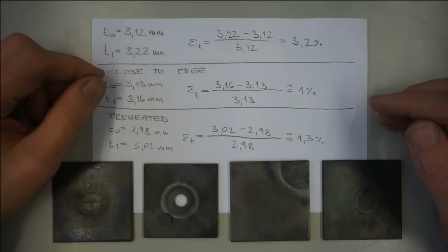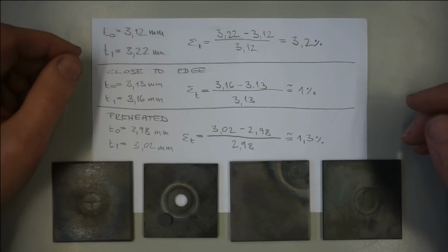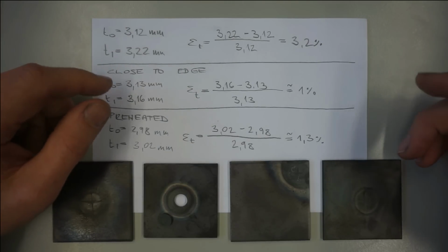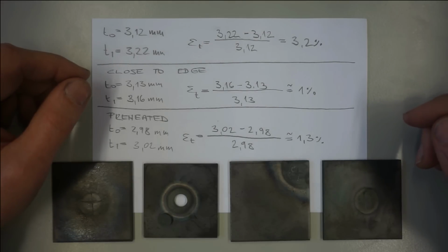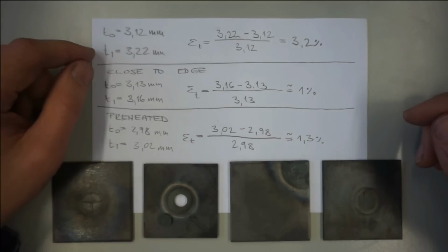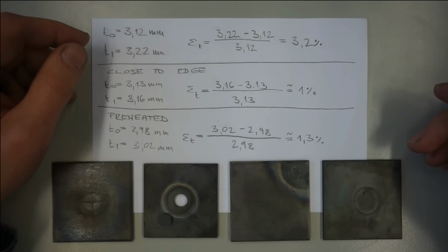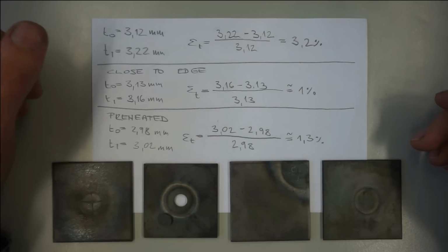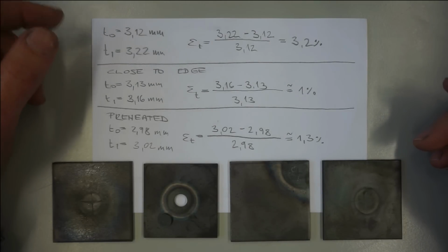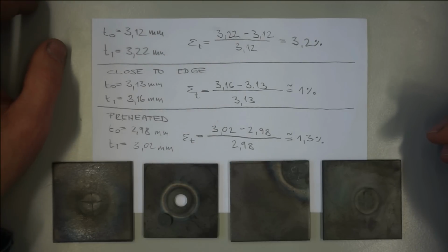You can try these experiments for yourself if you like, with steel or other metals. Also, you can vary the sheet thickness. Too thick sheets though are problematic to heat through, while too thin sheets tend to buckle. Nonetheless, if you compute the thickening in percent like we did earlier, you should find similar numbers and behavior as we got before. Higher percentages are typical for distortion susceptible materials and vice versa. But keep in mind that the heating temperature influences the result.